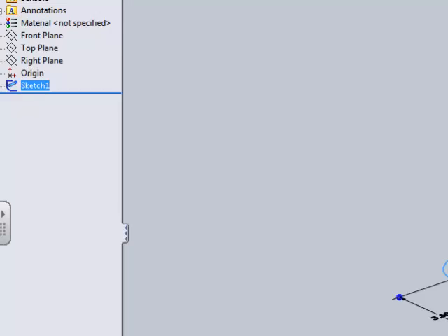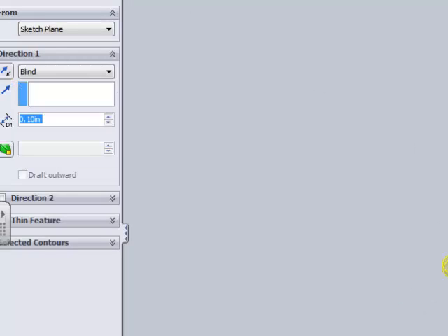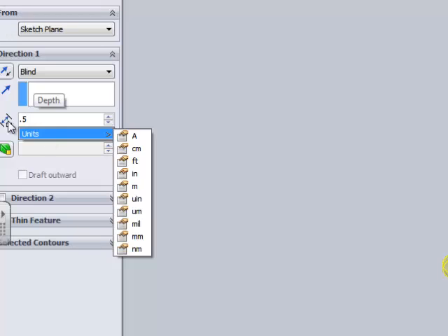You're better off just selecting the sketch, going to extrude, because otherwise it's going to extrude either the line or the circle. And we're going up 1/2 inch, so 0.5. In here, you can just type it in. It goes directly into that location. You don't have to click on it, because every click is an extra second, and that just adds up.